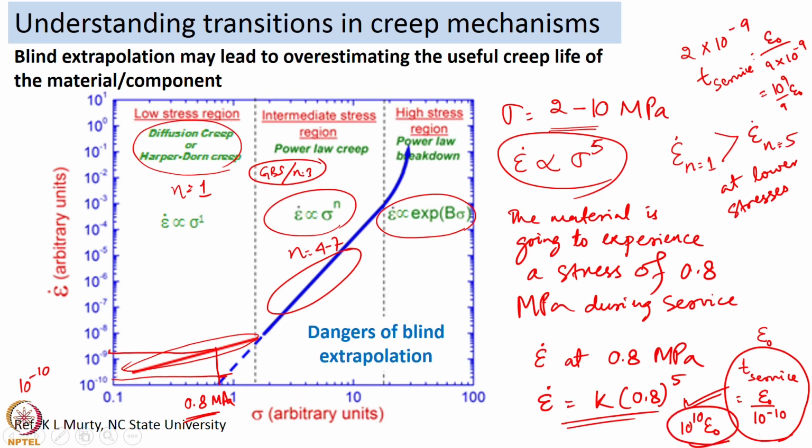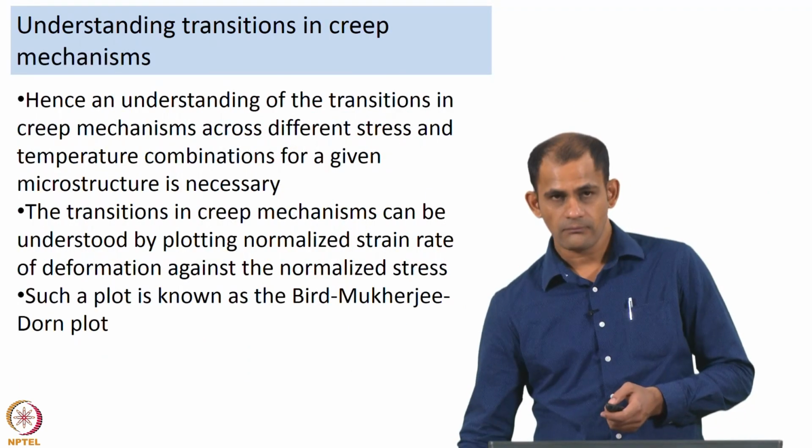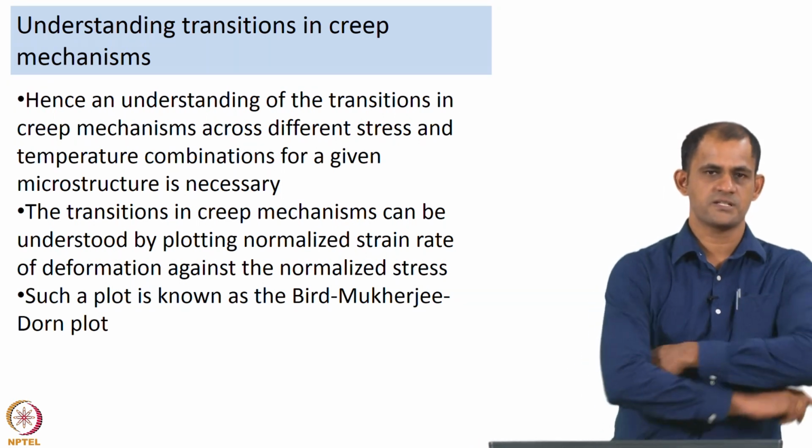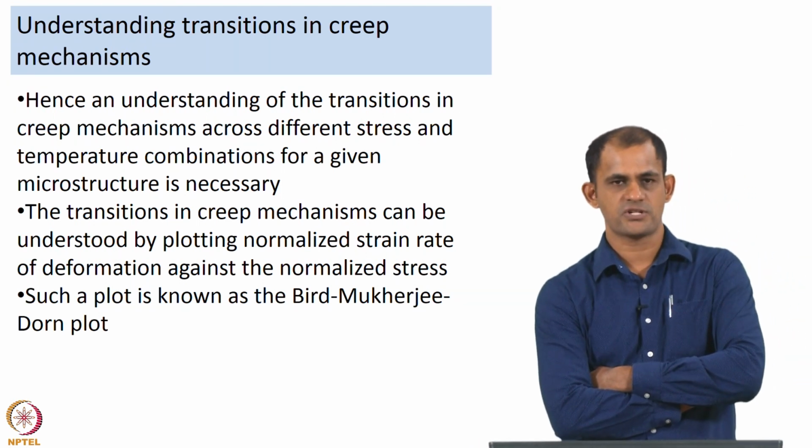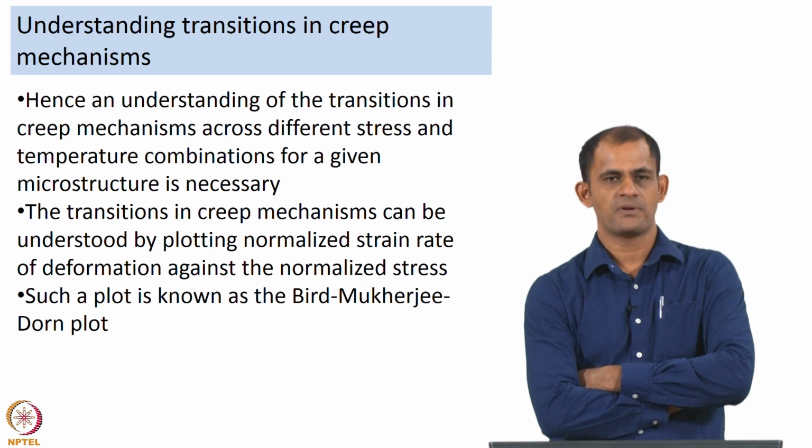from just blind extrapolation. So, the whole objective of this slide is to tell you that you should understand the deformation behavior of the material over different stress and temperature ranges and not rely on blind extrapolation, because you might significantly overestimate the useful creep life of your material by relying only on blind extrapolations. So, hence an understanding of the transitions in creep mechanisms across different stress and temperature combinations for a given microstructure is necessary.